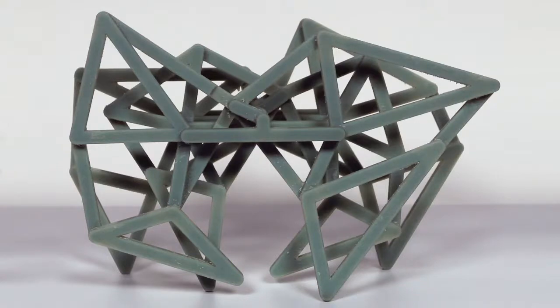And for these custom designs, 3D printing is the natural way of bringing them to reality. However, for these three things, we relied inherently on rigidity. And if we print them in the real world, we might find that some of these assumptions we were making don't really apply. Links that are too long and too slender are not going to be that rigid. They're going to be deforming. And the joints that we're using are also not ideal. There's going to be friction, there's going to be play, and all of these things add up to performance that might be pretty far away from what you thought you would be getting.